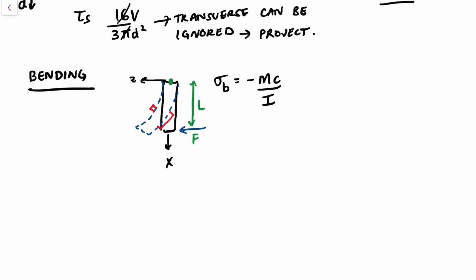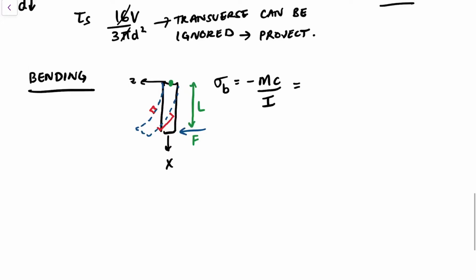And for a rounded shaft, we can make some assumptions, and it's also pretty evident that the maximum stress is going to occur at the outer surface. In this case it would be in compression here, but an element over here would be a little bit less compressed. An element here would be probably neutral with no stresses at all. And then somewhere down here would be even more extended. So your elements will be mostly compressed or in tension at their maximum value on the surface of the beam.